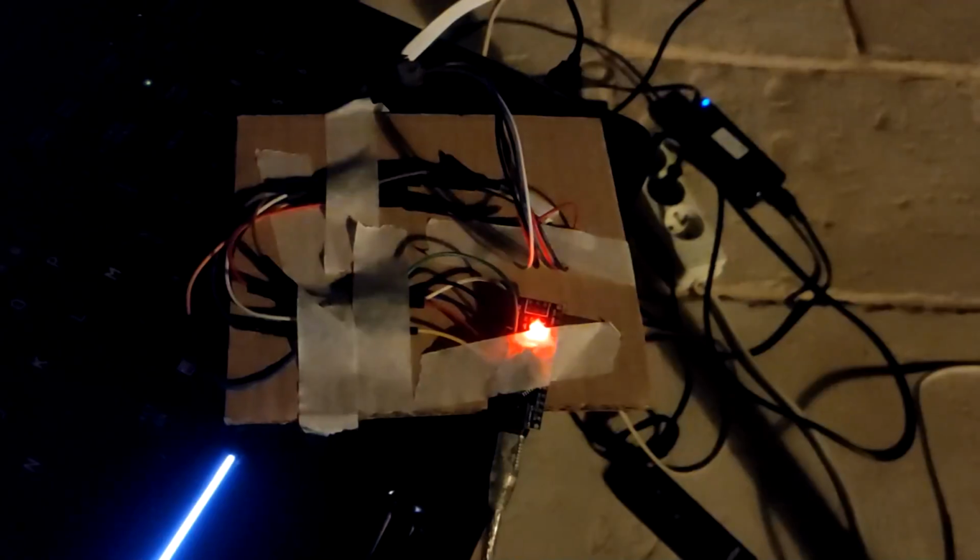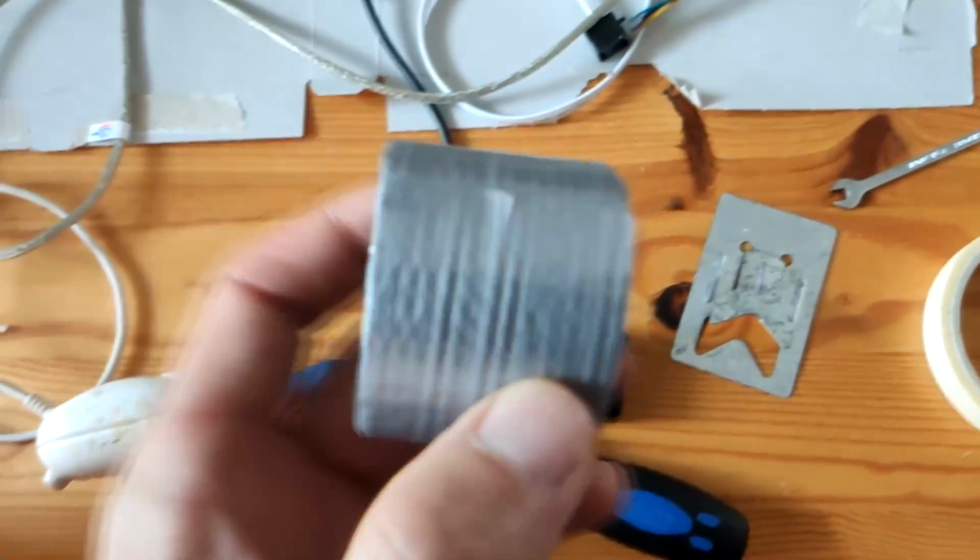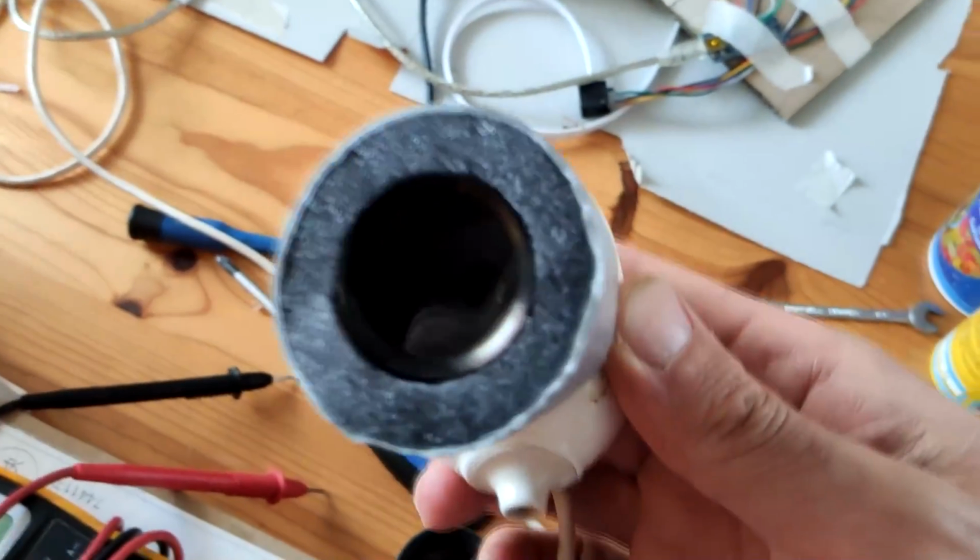I did the first Autoguiding test with the webcam mounted on the guide scope, but with the original code, as soon as I plugged the RJ12 connector, the guide star was gone out of the field, so the calibration became impossible. We just saw before that when we restore the tracking, the calibration may be possible. However, the Autoguiding wouldn't work because the mounting was imperfect. I used foam, tape and rubber bands to put the camera on the guide scope.